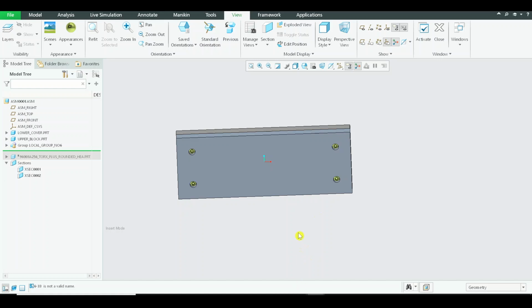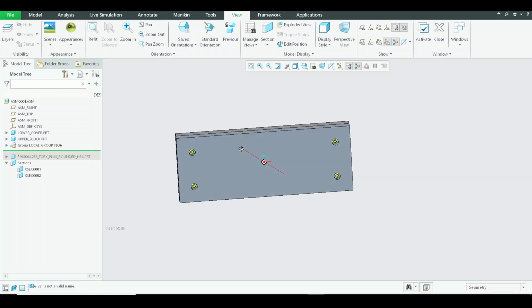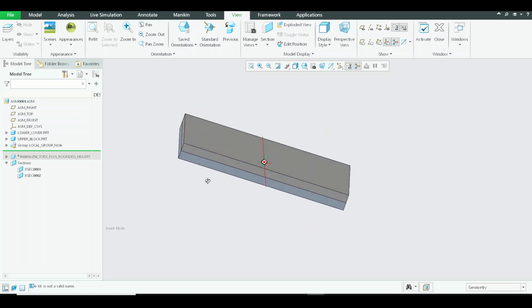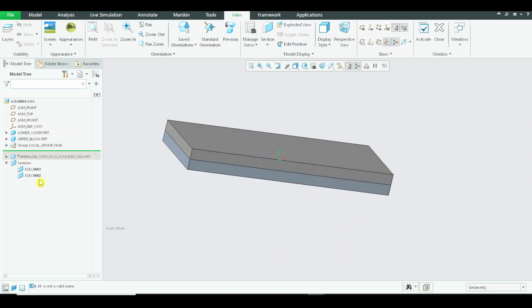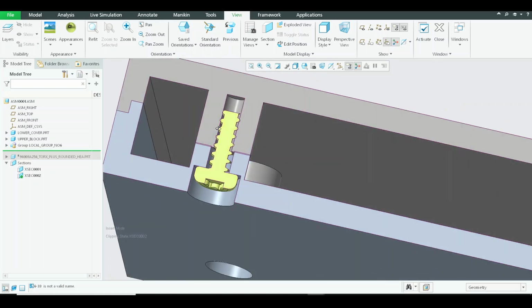All right, now it's not always desired to name it. I'm just doing it for simplicity, so don't get confused why it's not working. But we have added something over here. We have added the screw. Now the two covers can be assembled appropriately. Okay, now what are the surfaces of contact? The surfaces of contact are the bosses.